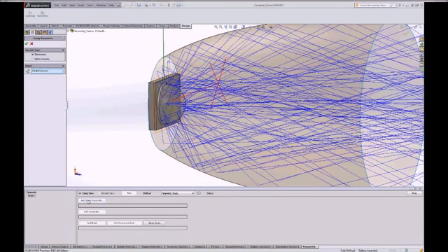I'm going to add a study parameter, and it knows that I had selected this particular distance. I could also do things like either dimensions or spline handles, any defined dimension within SOLIDWORKS. Okay, and here is my variable name, and I'm going to change the name to something that makes sense to me, LED position. And you'll notice that the original value is 0. And what I'm going to do is say go from minus 1.25 to plus 1.25.